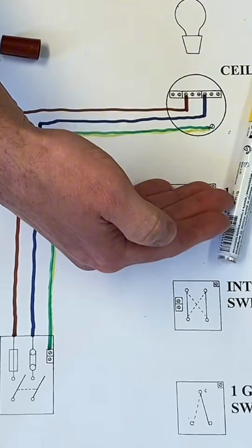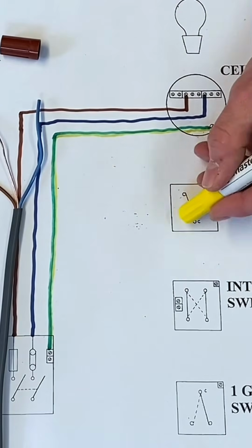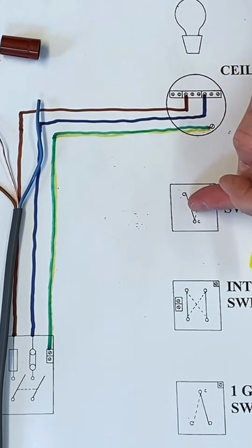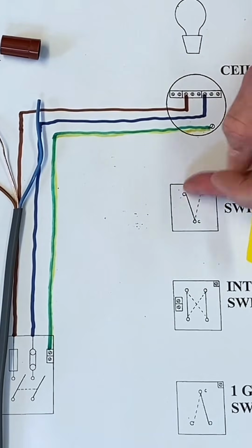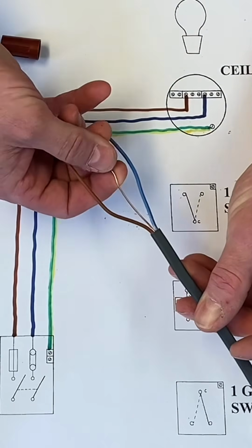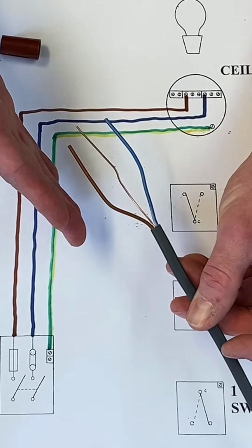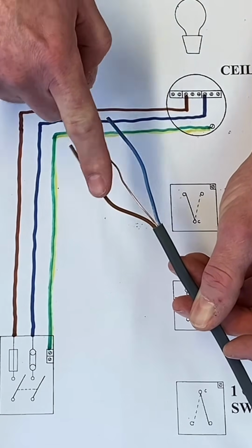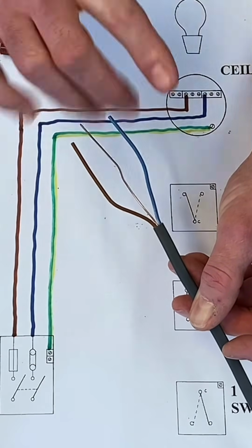And we're going to bring the cable down again as if we were going to a one-way switch or a two-way switch in our previous drawings. Exactly the same. This cable comes down from the light to the switch. We're going to use twin and CPC cables. I mentioned it in a previous video, but somebody commented we could use twin brown here. And we do often at Tresham use twin brown. So rather than using blue, brown and CPC, we use brown, brown and CPC.